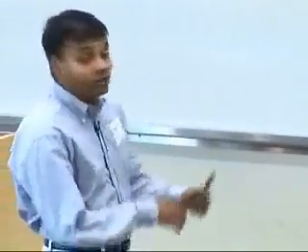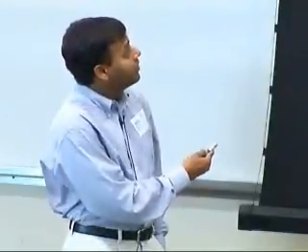And although the rate of upsets is much lower, so maybe it's like for 5% of the cases or maybe 1% of the cases you will see single event multiple upsets. So still I could say, well, I am okay with respect to 20x or something like that. On the next slide I have some actual data for BISER that I will share with you. But the big comment is that the single error assumption is clearly not sufficient.